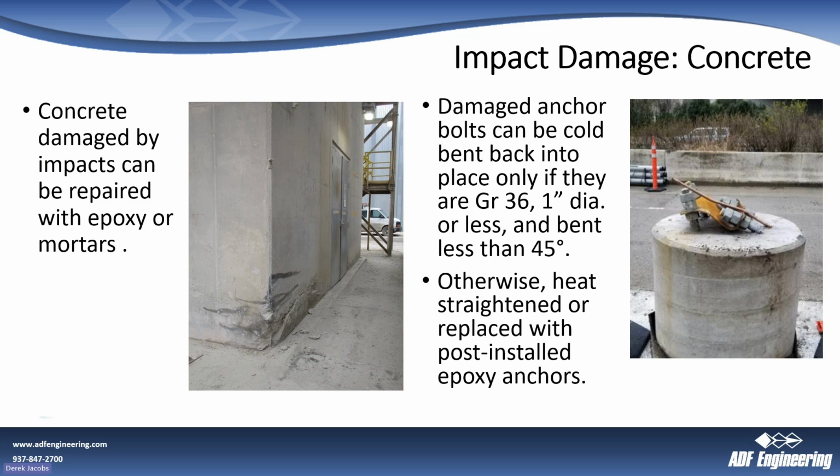Concrete can be damaged too. There's a little corner here that looks like it's been smacked by a couple different fork trucks. The repair for that will depend on what that damage ends up looking like. If it's a crack, you can usually epoxy it. If it's a larger chunk that got knocked off, they might have to put a form down and repair it with a mortar. If it's significantly large, maybe even some additional reinforcement to dowel in to hold that repair section in place.